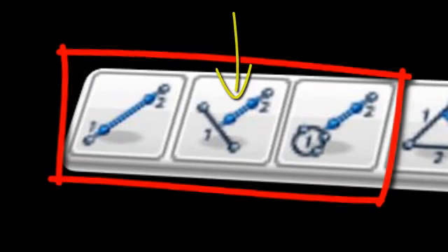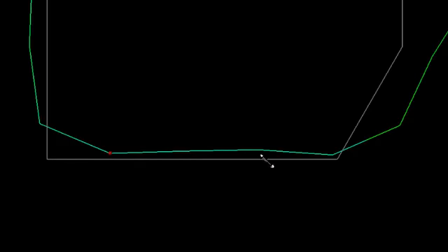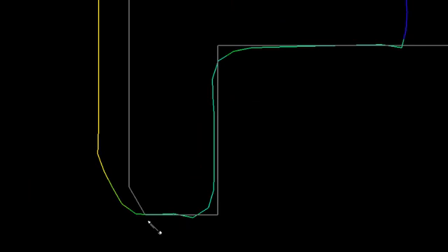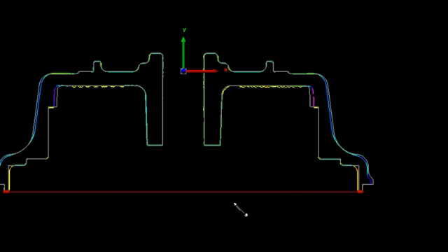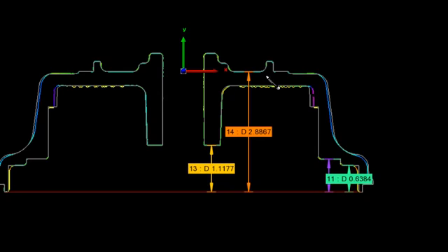Point-to-line distance. First, define the line by selecting at least 2 points to create your line. As soon as a minimum of 2 points have been selected, you will see a line best fit to those points. You may best fit to as many points as you desire. Right-click when the line is complete. Next, select a point to measure the distance from the line you created. Each point selected will create a new measurement feature in the tree. You can also define axis and plane constraints to these measurements. Right-click to exit the mode.